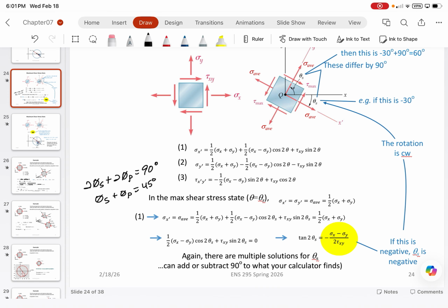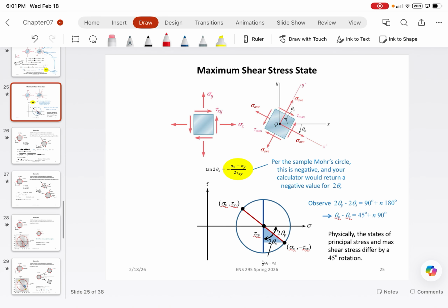This is simply another way of saying that for Mohr circle, this condition here is 45 degrees in the real world. It's confusing, very confusing, matter of fact, but just remember that when you're using Mohr circle to rotate everything, use 2 theta, not theta. Otherwise, you're considering the rotation as half what it should be. Does that make sense? All right.